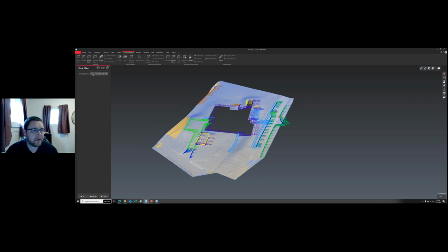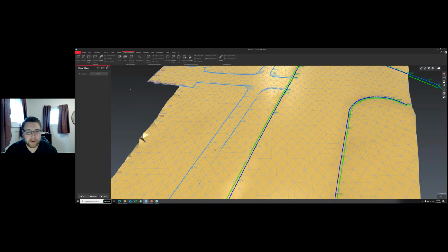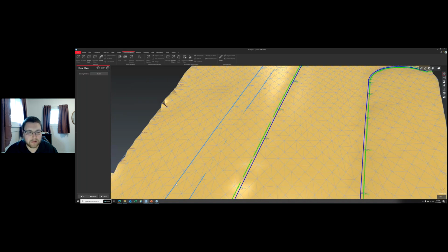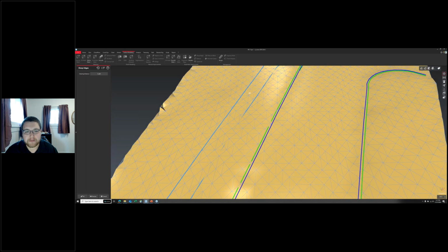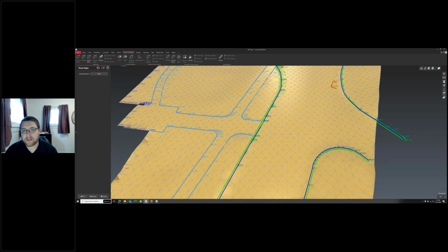When you run the sharp edges tool, the only option you have is a cleaning distance. If there are any triangles within this amount of space of the lines that you're adding, it's going to remove them. That's when it becomes helpful, because of things like the sidewalk here. There are a lot of extra points on these sidewalks, but because I drew each side of the sidewalks, these are probably a lot of points I don't actually need. The civil engineers who are going to use this for a design are happy with just having the two edges of the sidewalk and calling that good enough, so they can get a cross slope with it nice and easy.